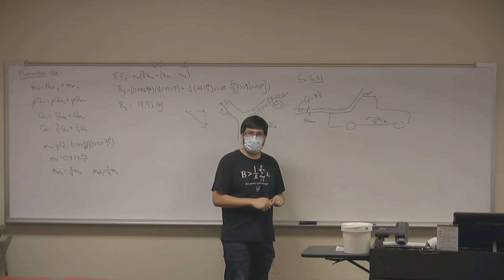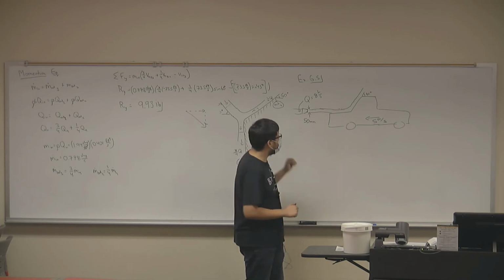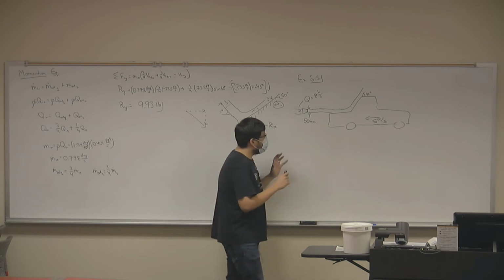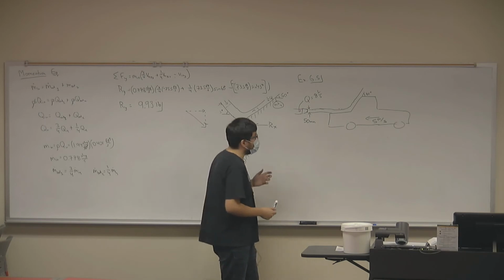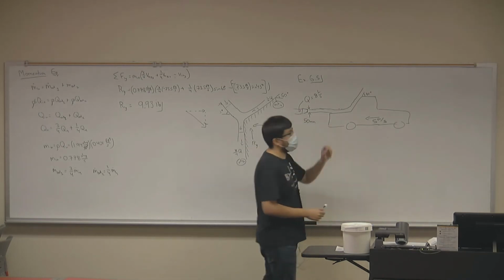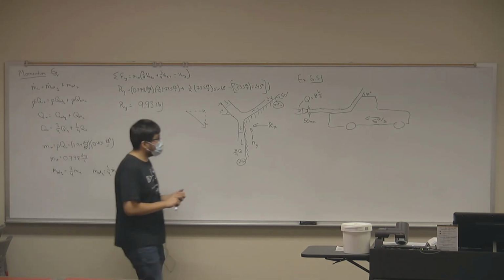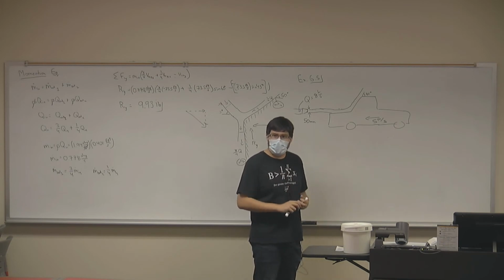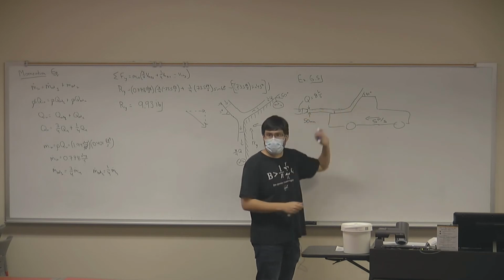So you're washing your car. You're pointing this hose at the car, which is moving towards you at 11 miles an hour. Okay? The question is, what is the force that this windshield is experiencing? So first off, we look at this. Where should I place my control volume in order for me to be able to solve this system using the momentum equation? Start from the hose? It doesn't have to go that far, but start before the bend at least, right? Okay. All right, so before the 45-degree bend.